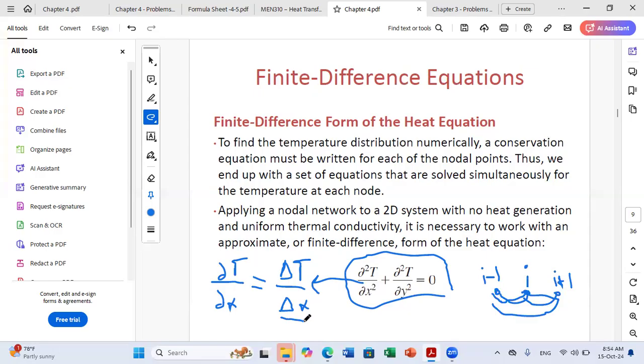So what formula to decide on depends on the physics of the problem. If you take a CFD course, you will learn, for example, that in case I have convection, the upwind scheme is better. In case I have conduction, I can take the centered scheme, etc. So depending on the physics of the problem, one method will be more accurate than the other.